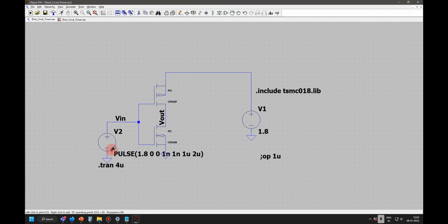No, delay is just shifting the waveform on the time axis towards the left or right. That is not propagation delay or something. It is only the input signal reference; we are adding some delay and setting a waveform. Let's not get into that. We'll think about the delay later. Delay is 0 in our cases. We'll start with that.